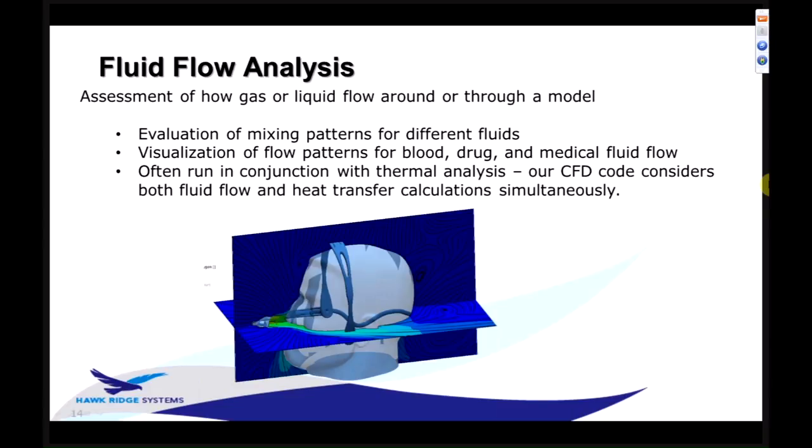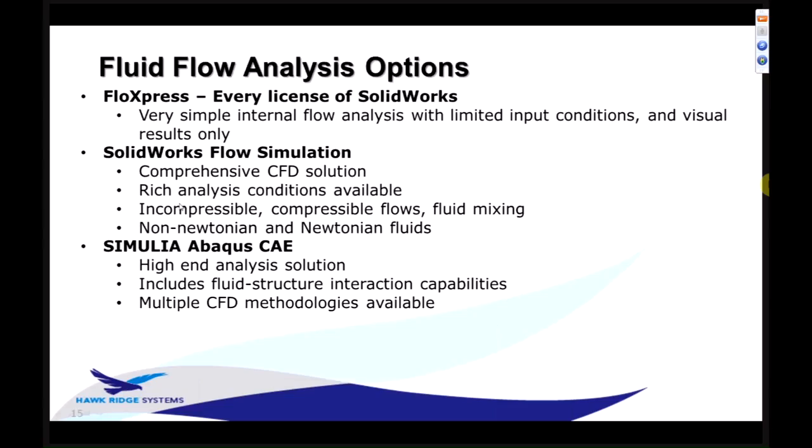We have three fluid flow analysis tools. The first one's in every license of SOLIDWORKS. It's called Flow Express. It does very simple internal flow, one inlet, one outlet, air or water only. And all you get as an output is a visual indication of the flow streams.